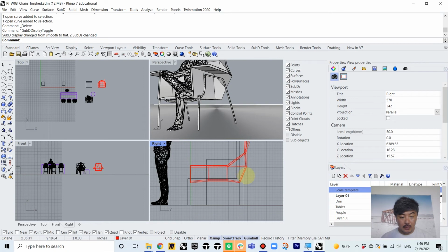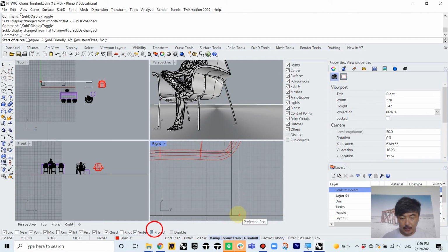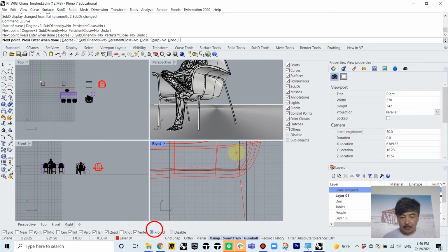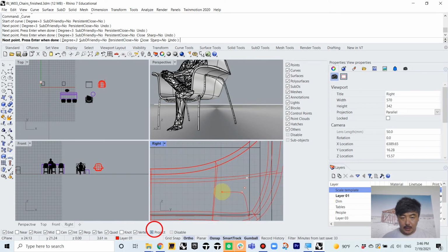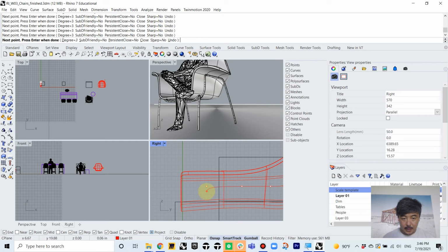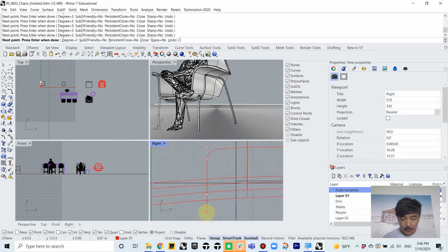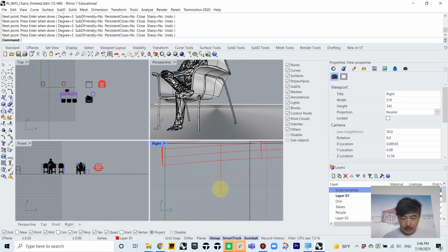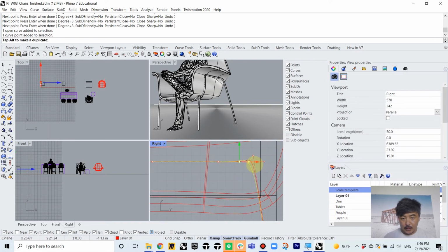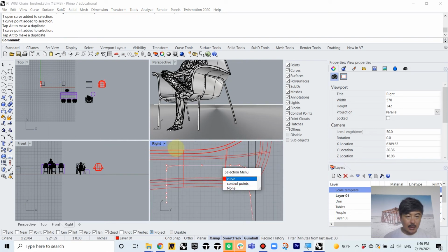And then use the control point curve tool to start from the side. Yeah, you can use the polyline tool to go up to it. Make sure that you turn on project snap on this so that it's going to draw these curves flat. And then give some control points and do some little adjustments here and there.